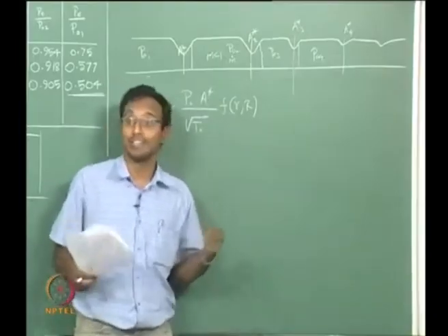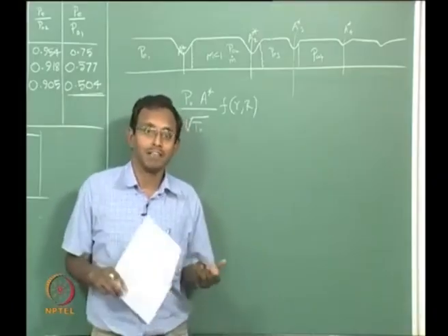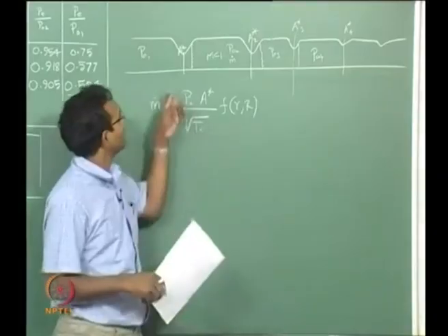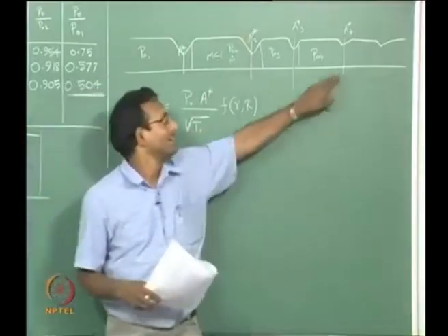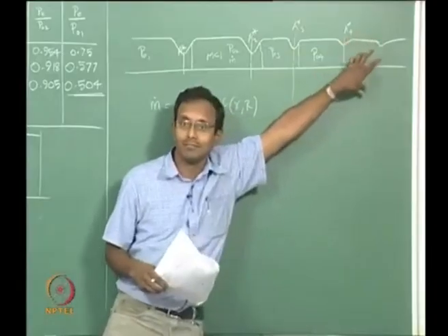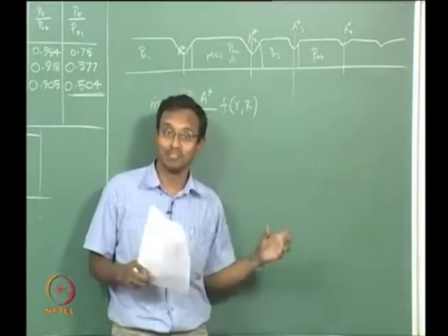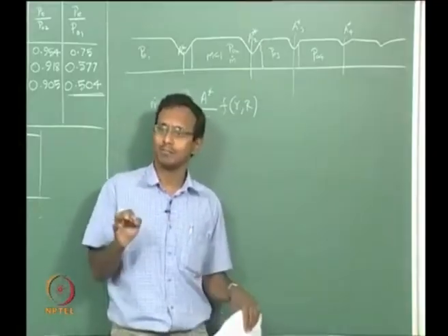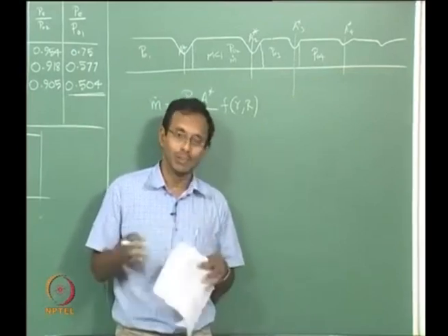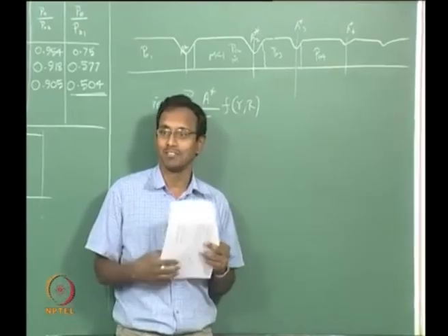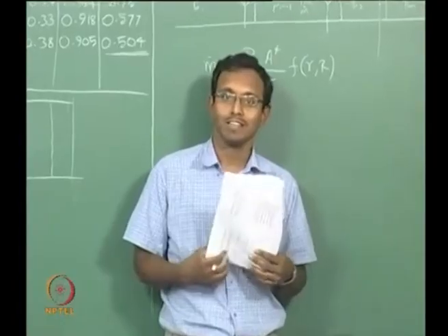In real life, if there is friction in the duct, there will be P0 loss because of friction also, because flow has to do work against friction. So my flow energy, the pressure energy is decreasing. If my pressure energy is decreasing, then it cannot go through that small area, it may need more area. There will be a point where that area will be equal to the duct area, and even the duct will get choked. That will be your limit. So, it cannot be infinite numbers, there will be a specific number for a given P01, that can also happen. Typically, you can choke flow 5 or 6 times, but it could be infinity if you assume no friction.